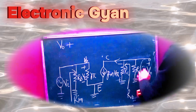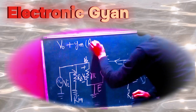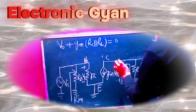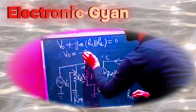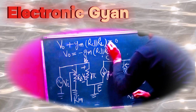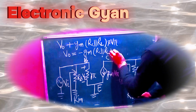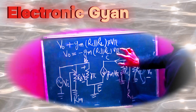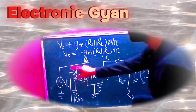V0 plus gm into RC parallel RL is equal to 0. So therefore V0 is equal to minus gm into RC parallel RL, and here is also into V pi. Now I want to find this value V pi in terms of Vi. So what is this?